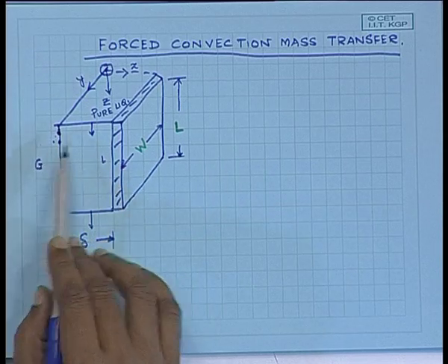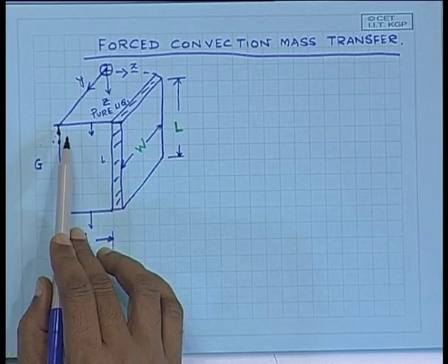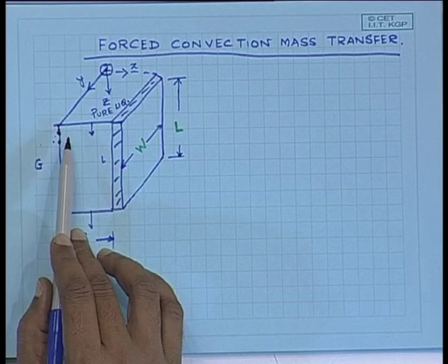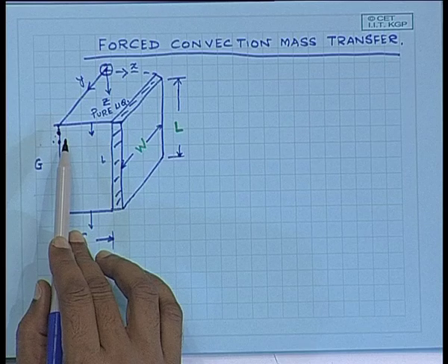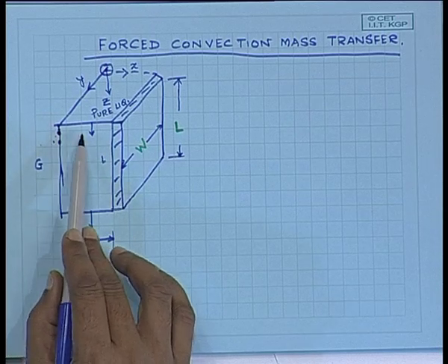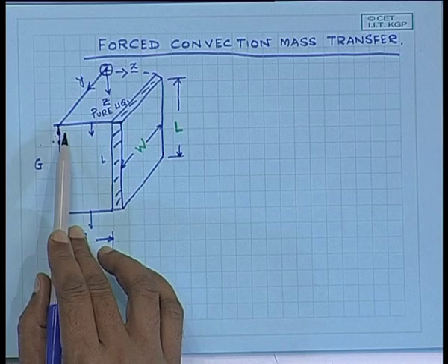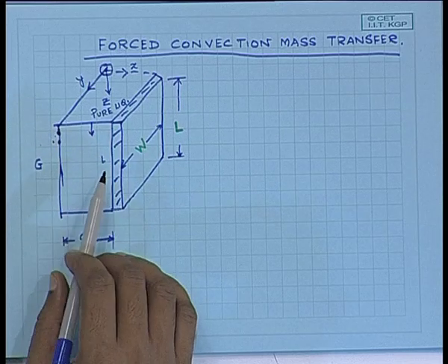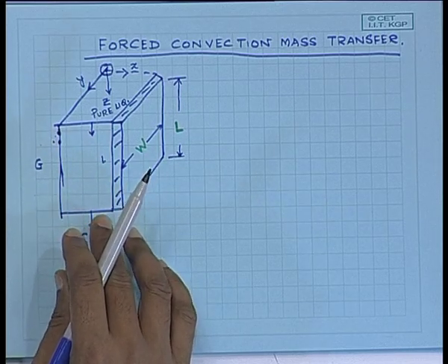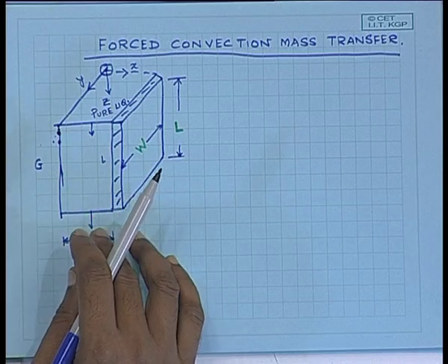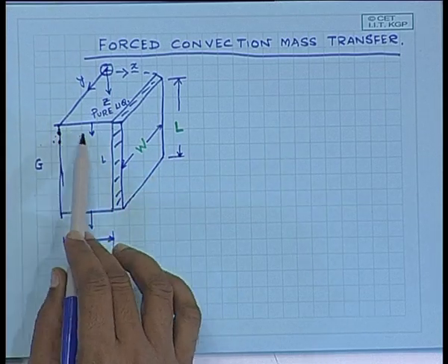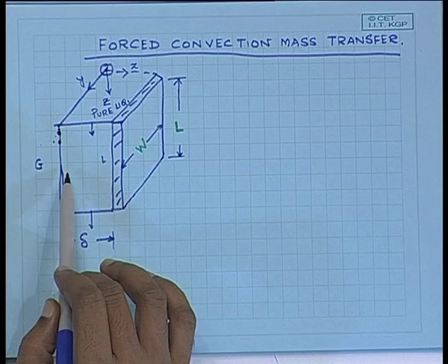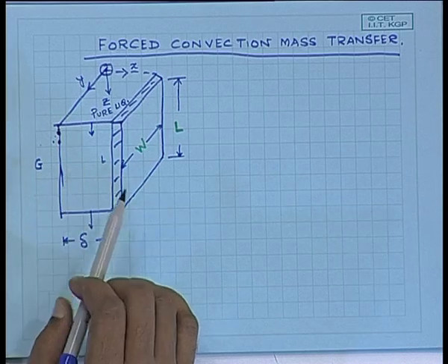Suppose this is ammonia and this is water. What is going to happen? Okay. So, if the solubility of the gas molecule is very high, then there is a possibility that such a situation may form in which there would be a flow in the plus x direction. So, right now the first restriction that we are putting on our system is that the gas is sparingly soluble in the liquid, as a result of which the principal flow in the x direction is due to diffusion, whereas the flow in the z direction is due to bulk flow.